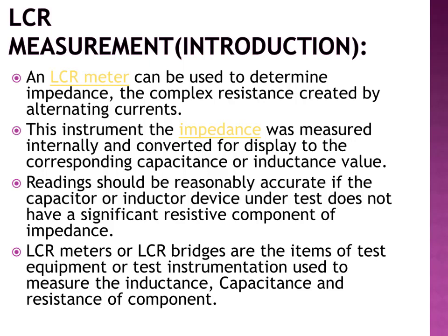Introduction. An LCR meter can be used to determine impedance, the complex resistance created by alternating currents. The impedance is measured internally and converted for display to the corresponding capacitance or inductance value. Readings should be reasonably accurate if the capacitor or inductor device under test does not have a significant resistive component of impedance. LCR meters or LCR bridges are items of test equipment or test instrumentation used to measure the inductance, capacitance and resistance of a component.